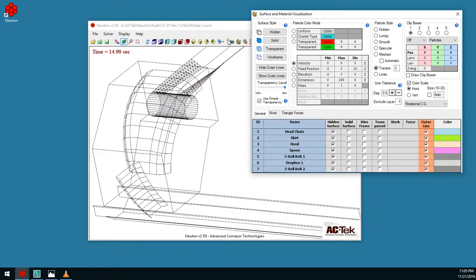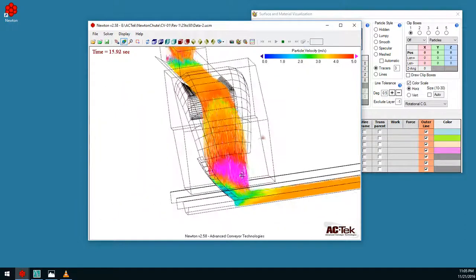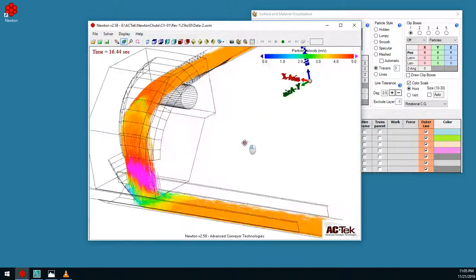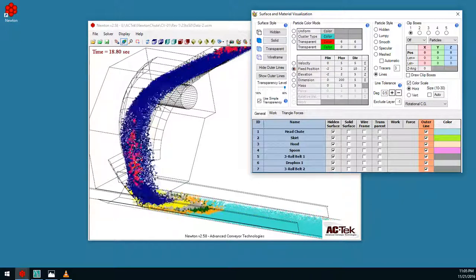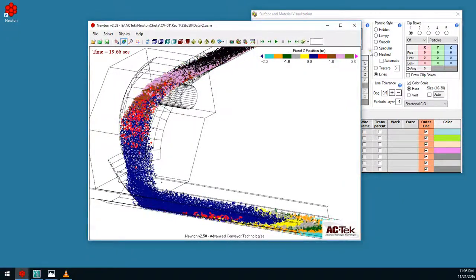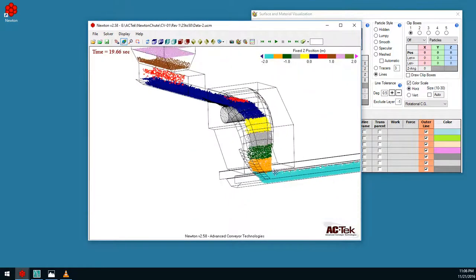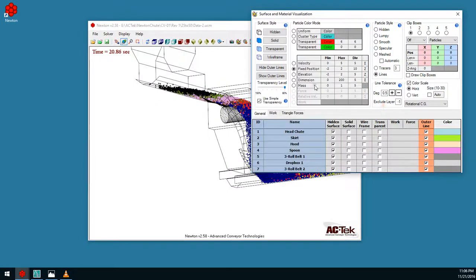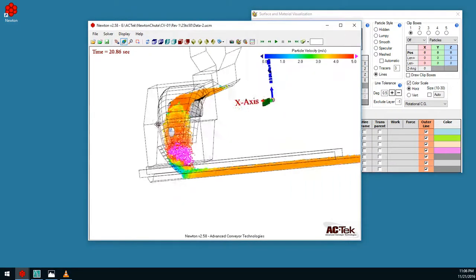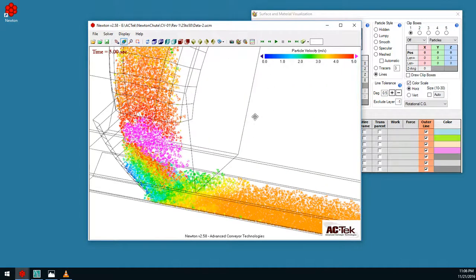You could add velocity tracers with that. This is a useful view of tracing the velocity positions, and you can change properties of the tracers and whatnot. We can color by a fixed Z position. Again, if I fix that Z position, you can see it essentially just colors all of the particles by their current Z position and then tracks those through the flow. So there's really just a whole different range of visualization parameters that we can work with.